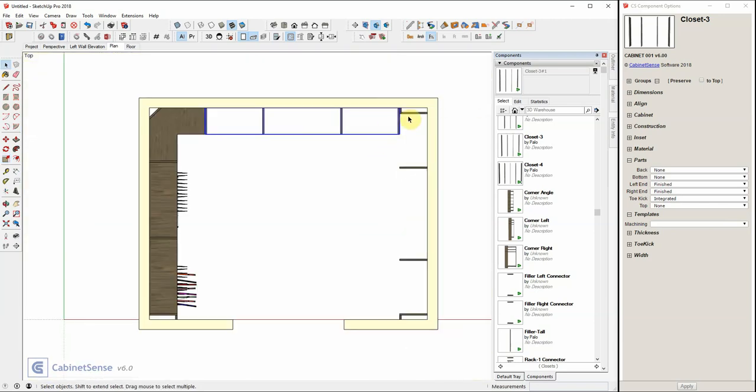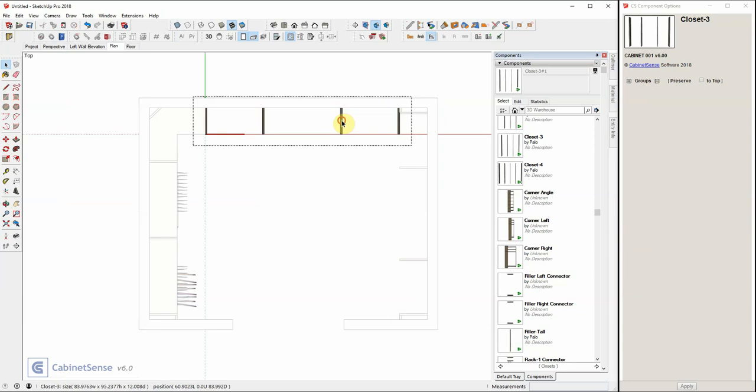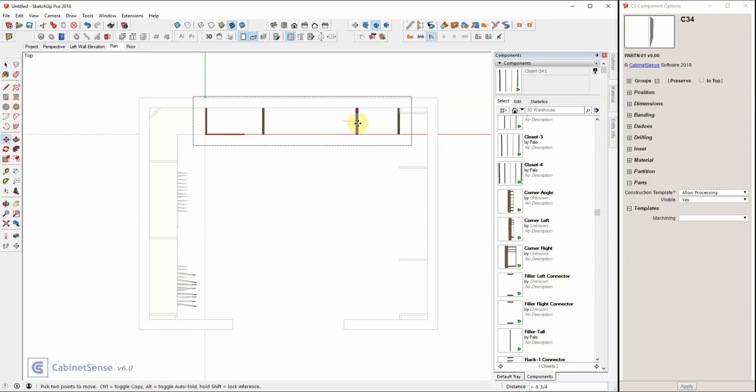One of the things, because we're going to have clothes here, we need a little bit of a filler space so that when our clothes overhang, it's not hitting this end panel. And so in fact, what we're going to do is we'll put a filler piece in here, but that means we'll need a 4-bay component. I could remove this, put in a 4-bay. I can also place the cabinet into Edit, drag the partition, make a copy, and drop it. And now inside the right side, I'm going to go back, find the filler that I want, and drop it in.